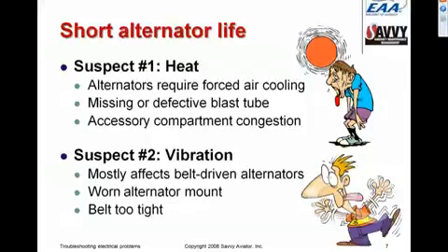We see vibration-induced failures more often with belt-driven alternators than with gear-driven ones, because the belt-driven alternators typically are mounted on some sort of a shock mount, and if there's a problem with the mount, or the bolts aren't torqued properly, or the belt tension isn't correct, the alternators can vibrate pretty badly when the engine is running, and vibration like that will cause premature alternator failures.